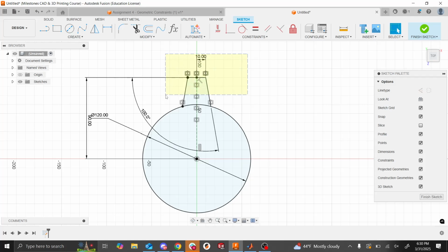If you highlight and the box is yellow, then it'll select anything that the box touches. Because I'm highlighting these lines, they will all be selected. You can see this vertical line is selected. But if I highlight in the other direction and it's this orange color, it'll only select things that are fully inside the box, right?